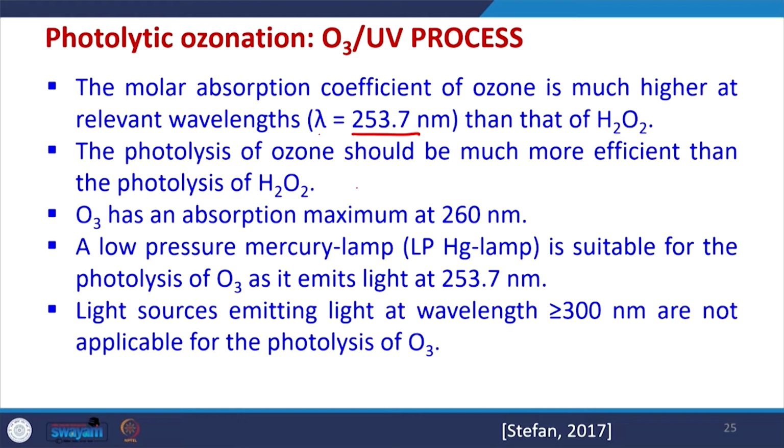This is the reason that O3 in combination with UV can be a highly beneficial as well as highly efficient process for wastewater treatment. Now, O3 has an absorption maximum at 260 nanometers, whereas the wavelength for usual pathogen destruction is 253.7, so the difference is not much.